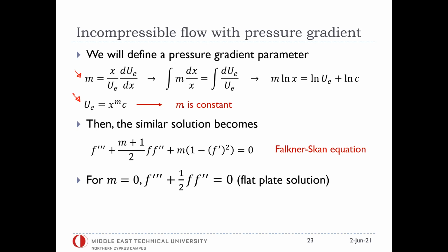Now, if I invoke this information into our similarity solution, meaning the Blasius approach, again defining a coordinate transformation, a stream function, and an f function similar to what we did before, we obtain a new ordinary differential equation for f.